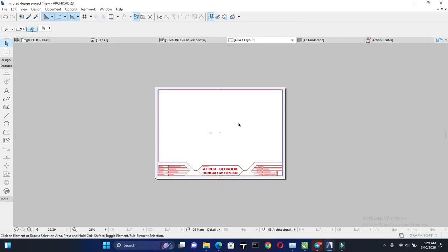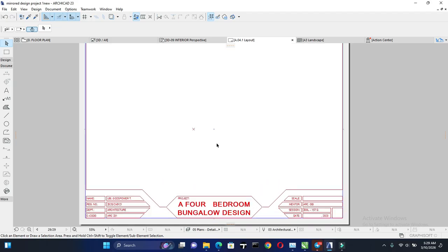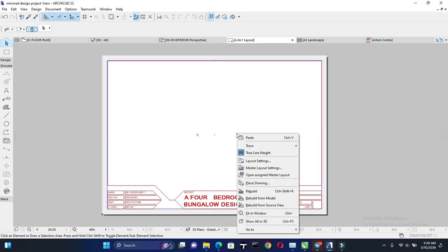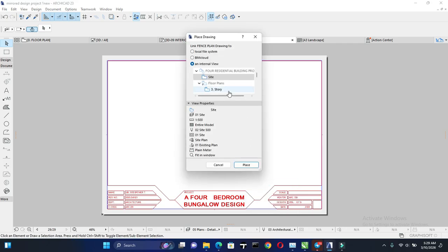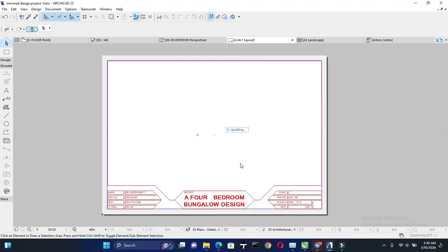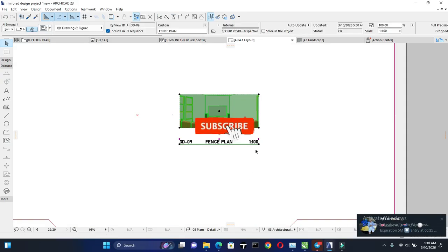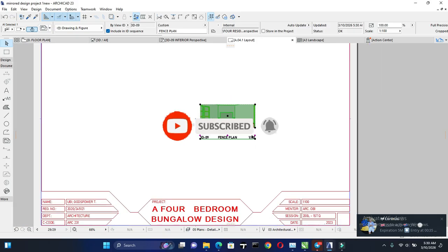So this is in a scale of 1:100. If I change the scale to 1:50, it will be bigger. Change it to 1:20, way bigger. So I think 1:20 will work for me, and move it to where it should be. Alright, so I think I have my view there. I can choose to edit the boundaries, or move the whole view. So any of it that you feel you can do, it's okay.